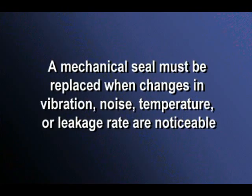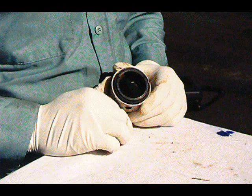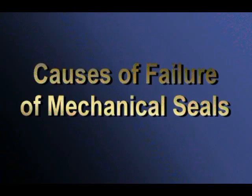Generally, a mechanical seal must be replaced when changes in vibration, noise, temperature, or leakage rate are noticeable. Any of these signs is an indication of excessive wearing of the surface. Factors other than normal wear and tear and scheduled maintenance may cause the failure of a mechanical seal. Each of these points is expanded on in the next section.